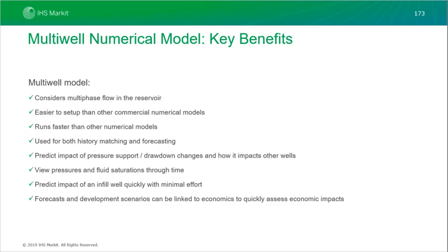In addition to this, the model can be used for both history matching and forecasting, and it can allow us to predict the impact of pressure support and how this impacts other wells. You can also view your pressure distributions and your fluid saturations through time, and you can forecast and develop scenarios which can easily be linked to economics to quickly assess your economic impacts. And we'll go into the software and actually take a look at a multi-well case.